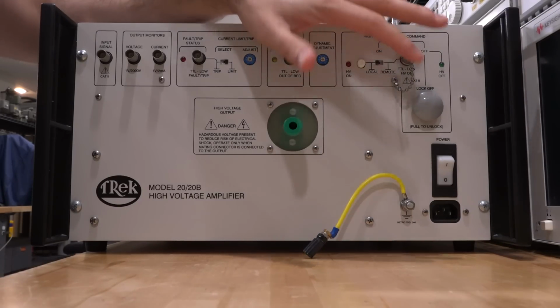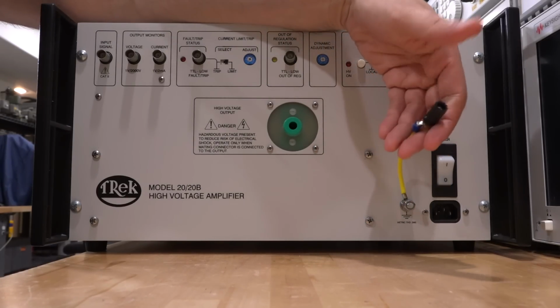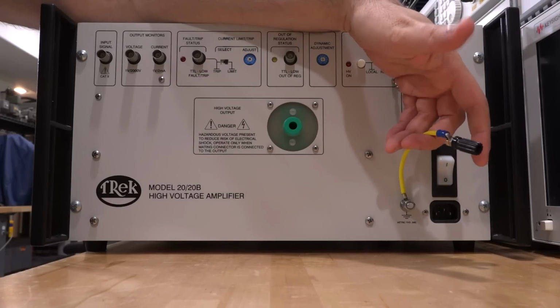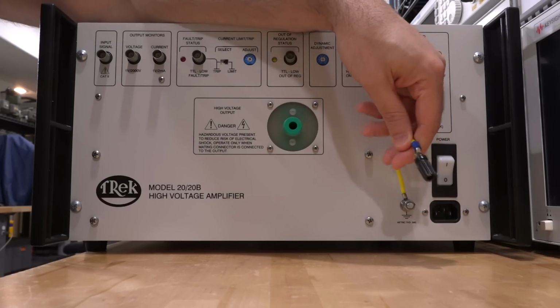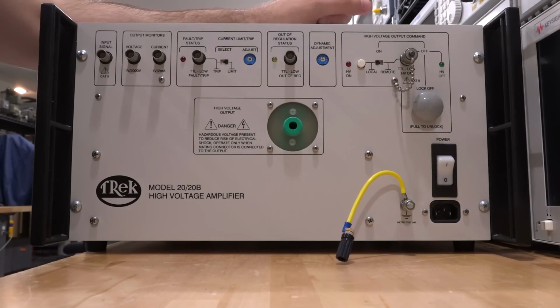The ground of the unit is the entire chassis. So there's a bolt in here to connect the ground. I have just connected this, but this is really not a very good way to connect this, because if you're relying on the ground to protect yourself, you want to make sure that this is solid, it is connected correctly. This is a reasonably solid connection, but generally you want a thick cable there too.